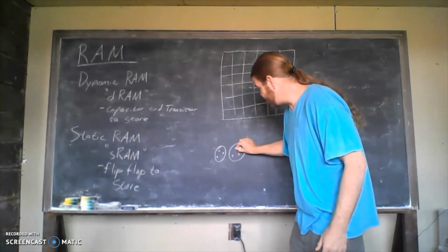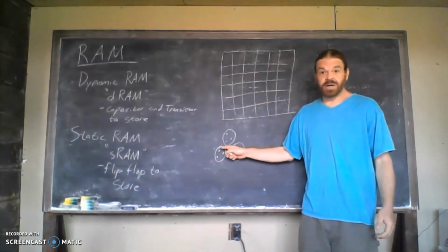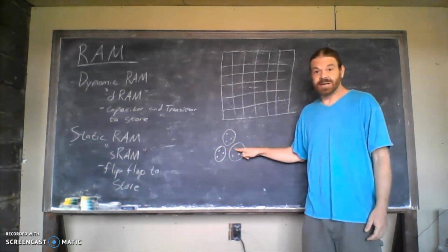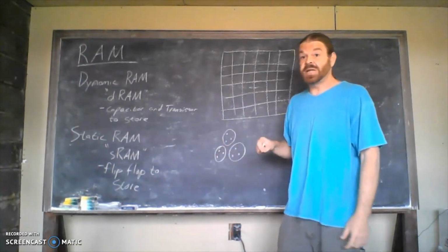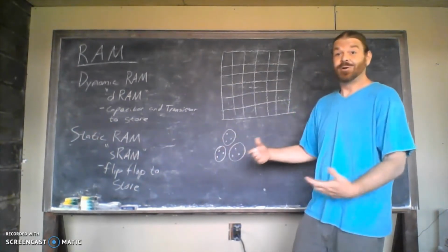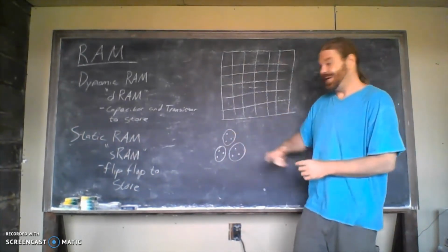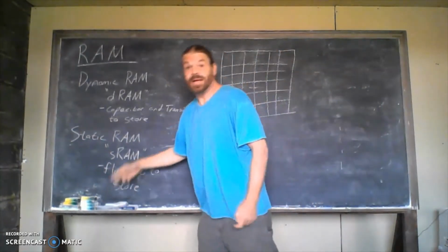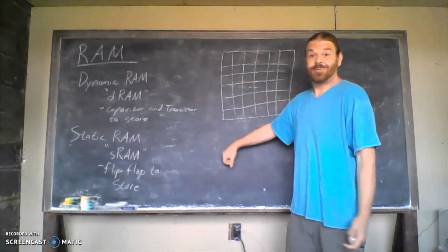So if we have several of them together, we can inadvertently create an extra one in between, because maybe we have a source, gate, and drain from different MOSFETs too close together and inadvertently create another MOSFET in between them. That's called a phantom transistor. So that's a big issue, getting into complicated electrical engineering, but that can also be taken advantage of, right? If we're having trouble positioning it, then maybe with those three we could add a fourth to use in between.